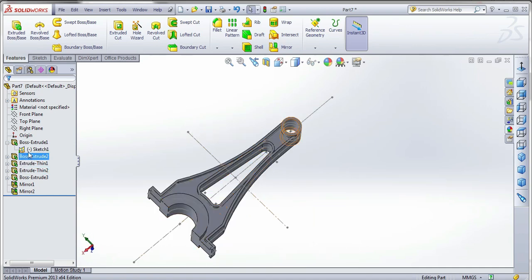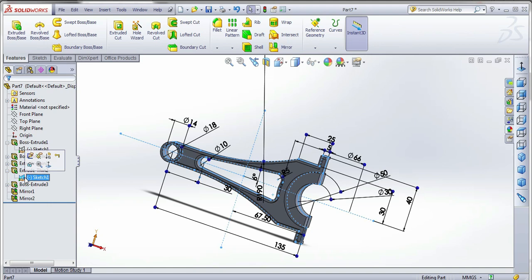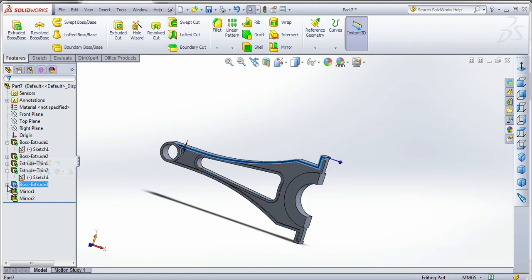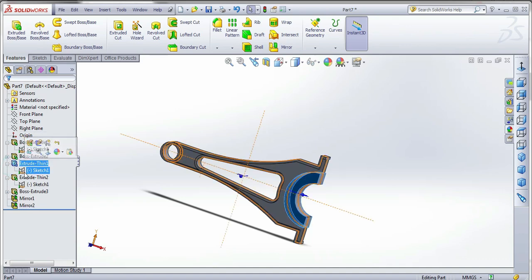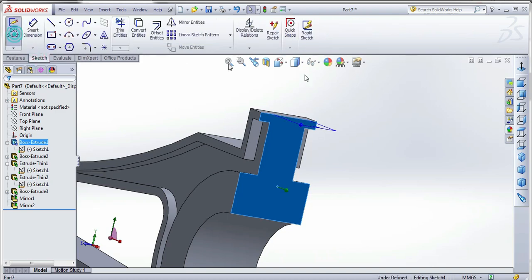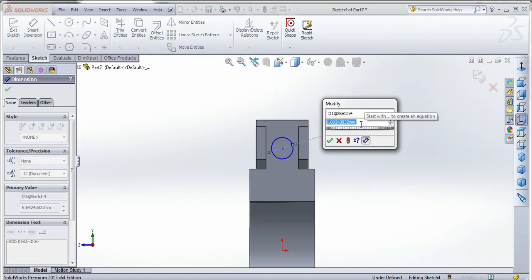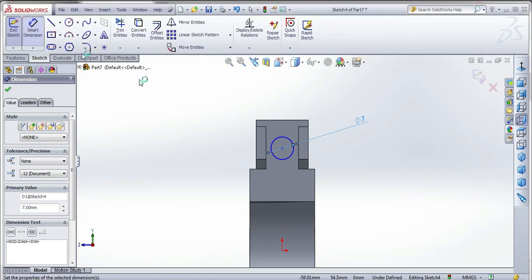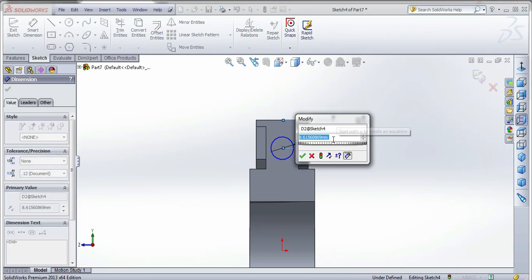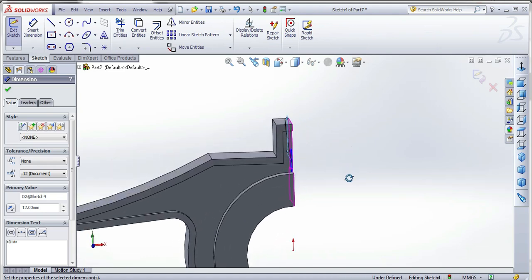Okay, it's behind. Make a connection of connecting rod top and connecting rod bottom. Both connecting rods should be coupled with a single pin. Listen, this entire thing is based on a single sketch. So it's very easy to draw by one method. We are going to draw the whole of the top connecting rod and bottom connecting rod location. This hole is based on that. This hole only connects the top connecting rod and bottom connecting rod. The circle diameter is 7. From the top surface, the circle diameter is 12. Circle length is 12.